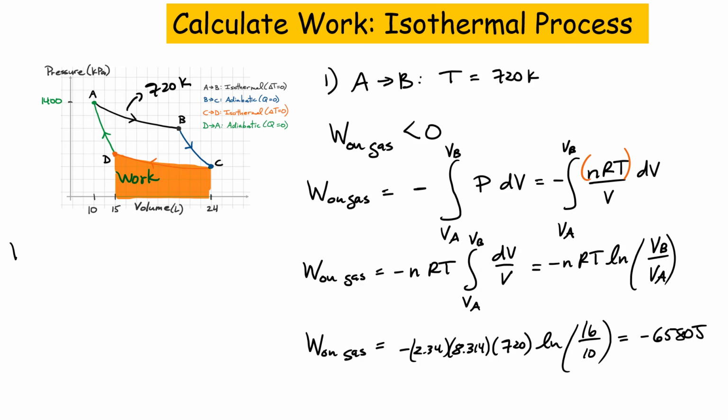Okay, so in that case, the work done, let's just go from C to D. The temperature for that isothermal process, this guy right here, all along there was 549 is what we had. So the work done on the gas for that case, again, it's minus nRT natural log. Now just make sure you have this right. My final here would be the volume at point D, and my initial here would be the volume at point C.